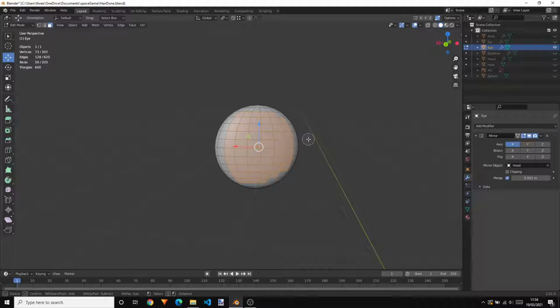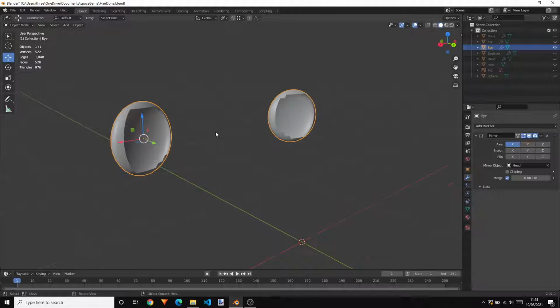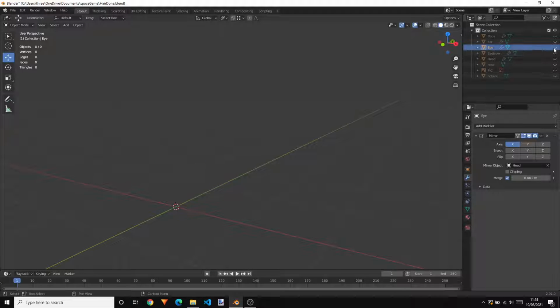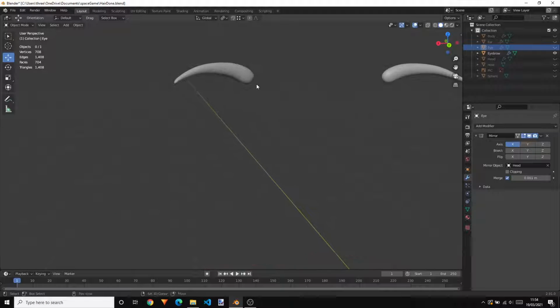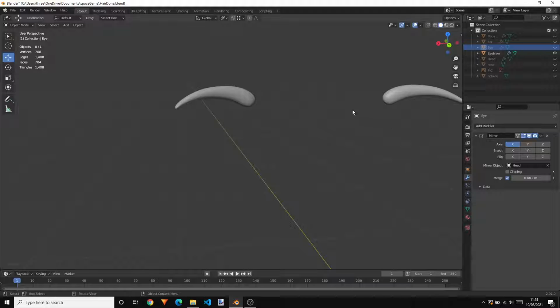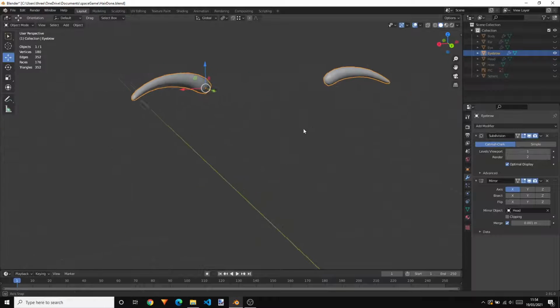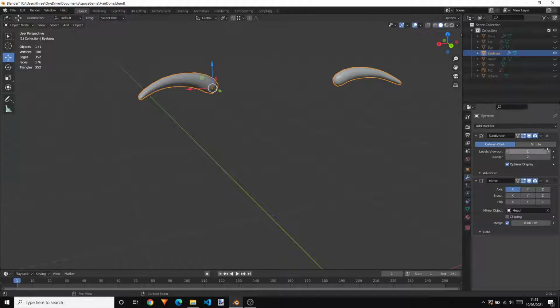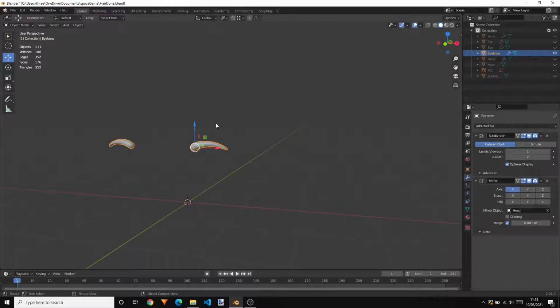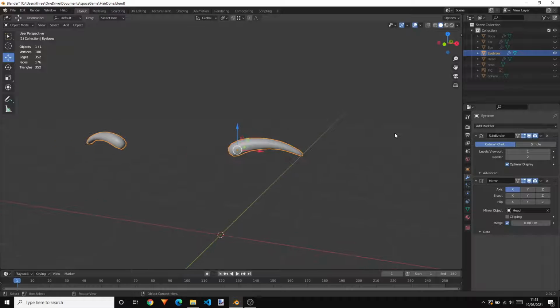So let's just say I want to select that, and then I want to press enter to get out of circle select mode, and then delete those faces. So at the moment we've got 56 selected. Let's delete those faces, and now you can see there's 528 altogether. So that's reduced the eyes. Eyebrows, you could probably go and do the same. So we've got a subdivision surface on this, so let's have a look what it looks like with one subdivision. We've got 176 faces compared with 704, so it's like, is that worth doing? Probably it is. Yeah, I'm probably going to do that.